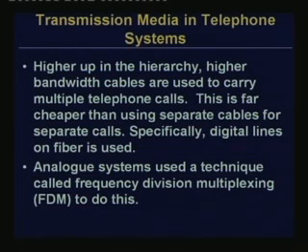Higher up in the hierarchy, higher bandwidth cables are used to carry multiple telephone calls. This is far cheaper than using separate cables for separate calls. Specifically, digital lines on fiber are used, and analog systems used a technique called frequency division multiplexing to do this. Nowadays, of course, time division multiplexing is the most dominant standard.